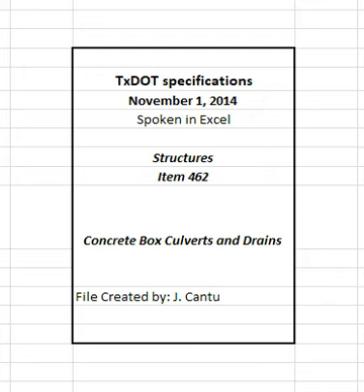Fine cracks on the surface of the member that do not extend to the plane of the nearest reinforcement are acceptable unless the cracks are numerous and extensive. Repair cracks that extend into the plane of the reinforcing steel in an approved manner. Excessive damage, honeycomb, or cracking will be subject to structural review. The engineer may accept boxes with repairs that are sound, properly finished, and cured in conformance with pertinent specifications.